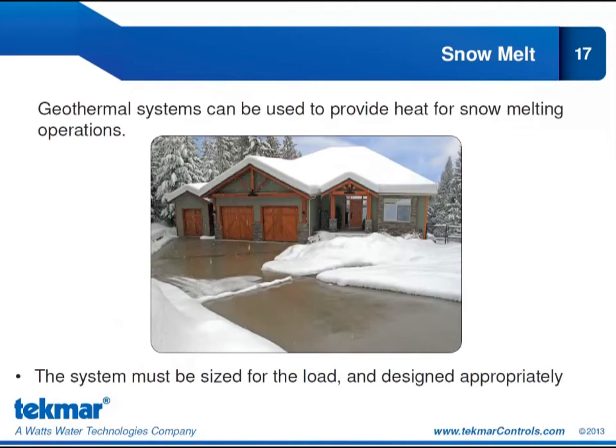Another high temperature application for a geothermal system is snowmelt. So yes, we can use a geothermal system for our snow melting needs, but we have to take care that we size the earth loop and the heat pump accordingly. If they are not sized accordingly, then we have to make sure that there is a backup heat source in play that can answer those needs.